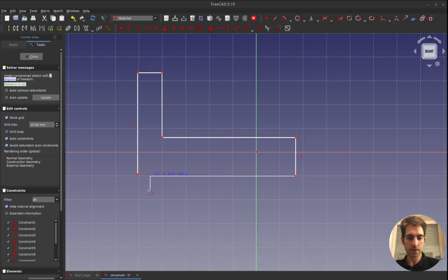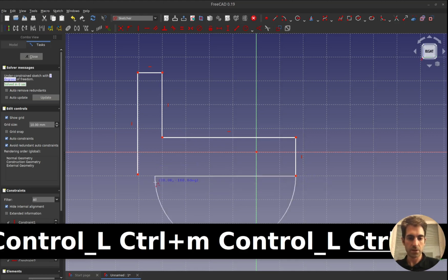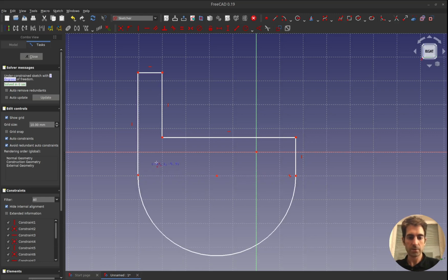You see, I can do two lines at the same time. I can also do Control M again, then it is changing again. I can do one more, it is changed. So there are more possibilities. If I use Control M, I can change from the multi-line to a multi-arc kind of solution. If you do a little bit of practice, it can be pretty handy to use this.